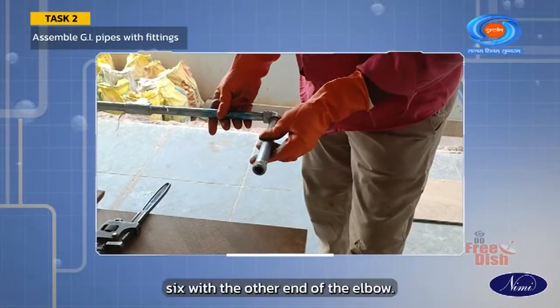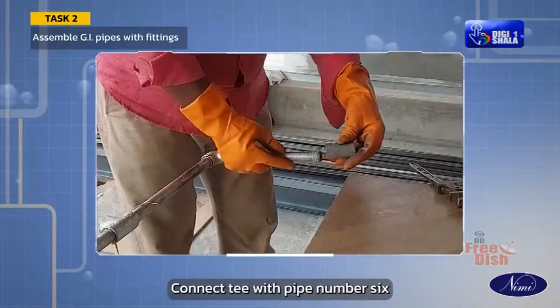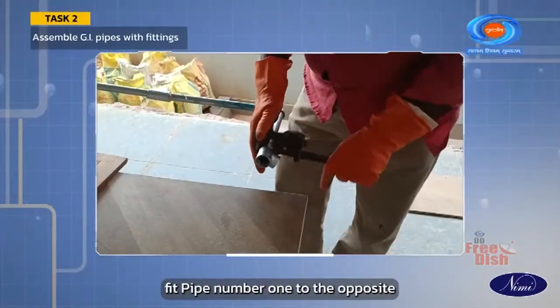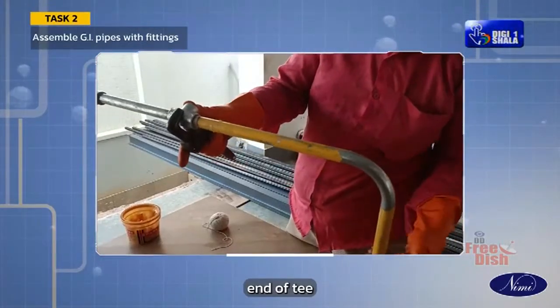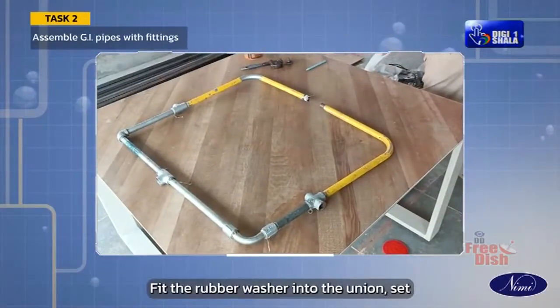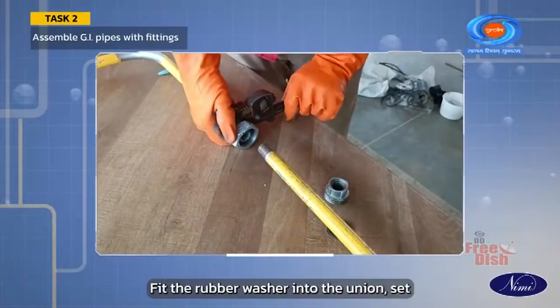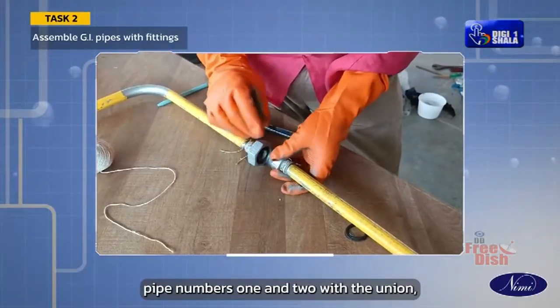Fit pipe number 6 with the other end of the elbow. Connect T with pipe number 6. Fit pipe number 1 to the opposite end of T. Fit the rubber washer into the union. Set pipe numbers 1 and 2 with the union.